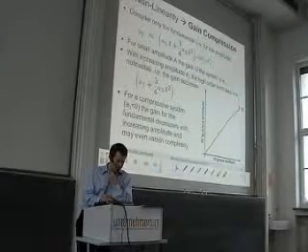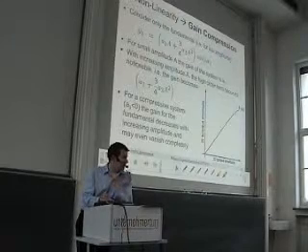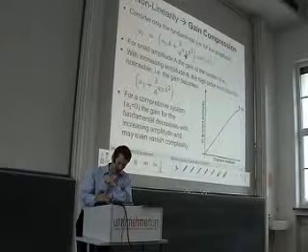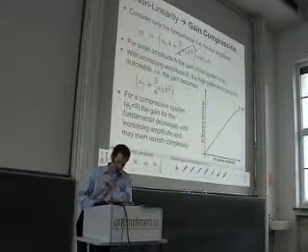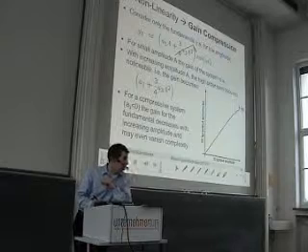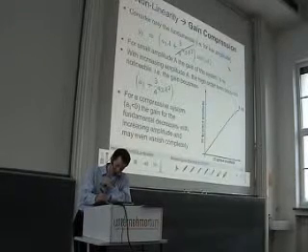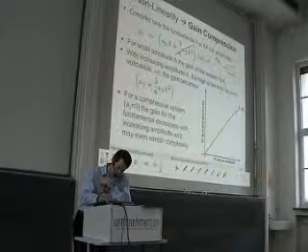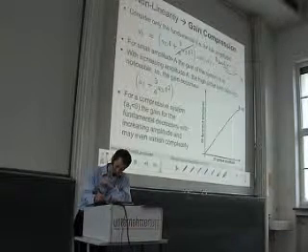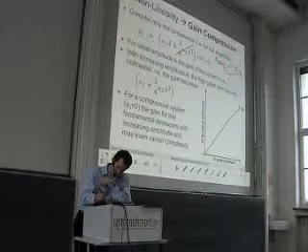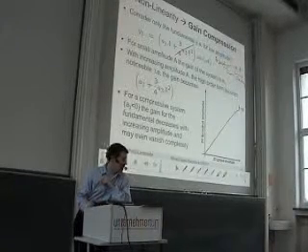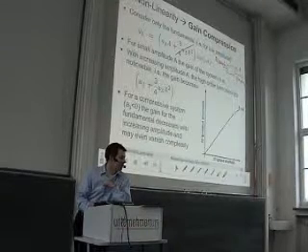If the amplitude is very, very small, then A to the power of 3 is even smaller than A, so I can neglect this. So I get a gain of a1. I have my system, I put in here A sine omega t, and what I get is a1 times A times sine omega t. This is for small amplitudes.